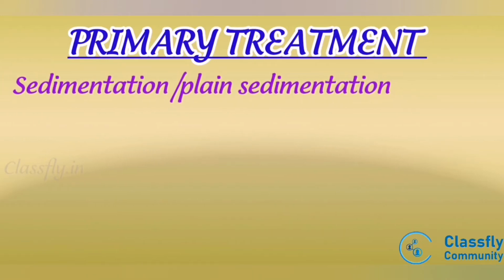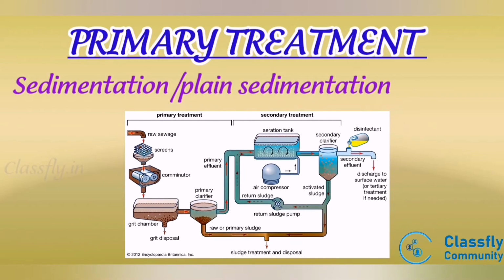Sedimentation or plain sedimentation means the screened water is passed into a sedimentation tank which has a V-shaped bottom provided with an opening. As water enters the tank from the bottom and slowly rises upwards, the solid impurities settle down due to gravity. Finally, the water is taken out of the tank and the solid particles in the form of sludge are removed from the bottom.